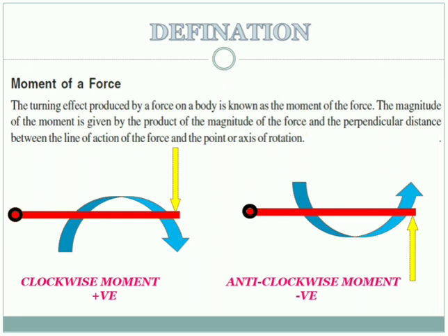Now if here again the value of the force was 10 units and the length of the beam was 5 units, what would happen here? Again the magnitude of the moment will be force into the distance, that is 10 into 5. But in the second case, where the force is acting from the bottom, the rotation caused is in anti-clockwise direction, hence it will be with the minus sign. Therefore our answer for the second case will be minus 50.